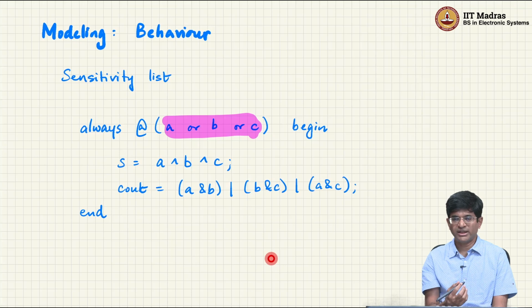The way to think about it, and you are probably familiar with the term RTL or register transfer level, is you should not think of these as programs that you are writing. You need to think of them literally as, I have a certain hardware that I have in mind. Like for the counter, I knew what I wanted. I knew that there should be a counter, I knew it should have an enable signal, an up down count signal and so on. And the rest of it was basically deciding how do I get that functionality.